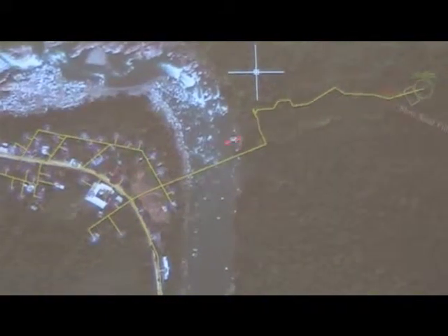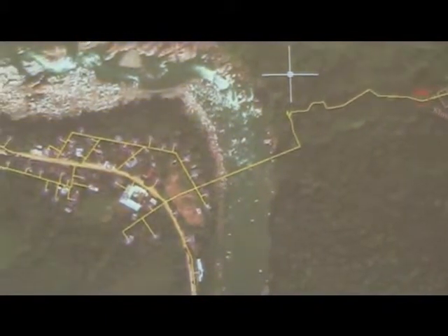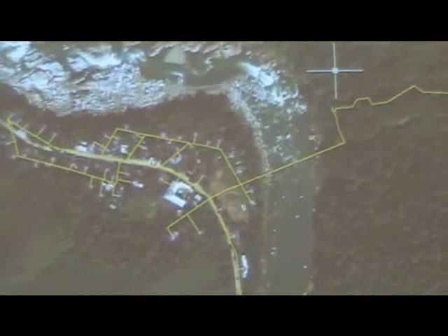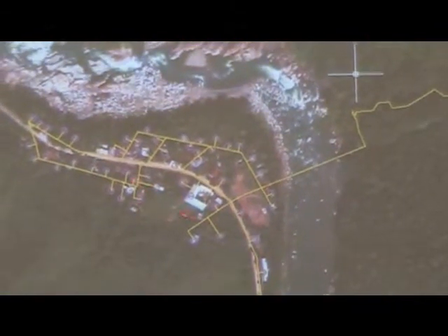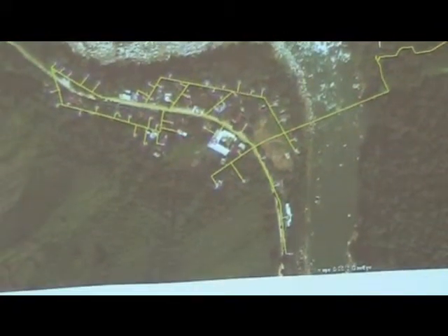This is right where it crosses the river. That's where the pipe will be steel. And then here is the town itself. Each pink circle represents a house. We tried to maximize looping, although the town is kind of linear. But along the road, that's where the cover will be 24 inches minimum. And looping was done to ensure that if there's ever any problems in the pipe and maintenance needs to be done, there are other routes that water can be received.